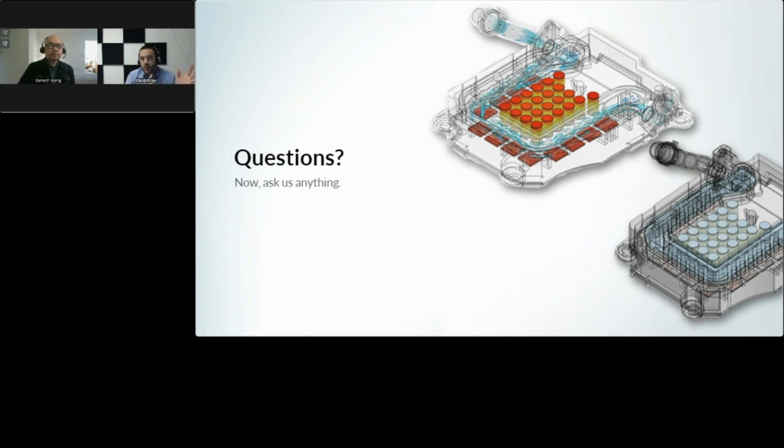But again, going back to what I said earlier, SimScale is about making simulation technically and economically more accessible. So we don't make any of these steps compulsory, where a user has to go through them, which is often the case in other software. Here, automation heuristics are being used to drive a very good mesh. But if a user is advanced enough or has a certain reason to drive a mesh manually, of course, this is possible.